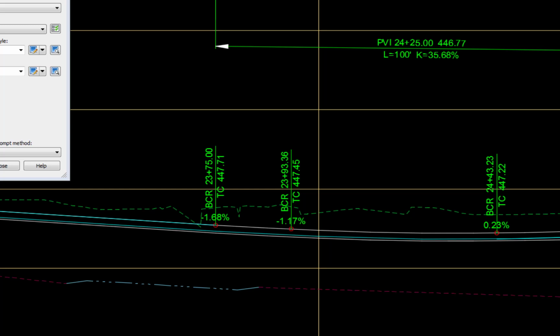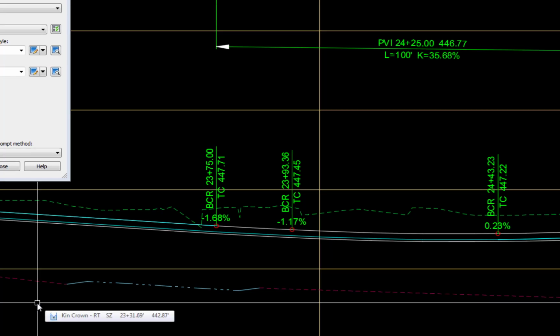And 2. In Properties dialog box, select the appropriate reference object from a drop list. When a label contains more than one reference, each reference is selected separately from a drop list. Where there is only one or few labels with question mark, it may be easier and quicker to erase the label and create a new label in its place rather than trying to correct the existing label. Watch the next video on using the Label Style Composer to create or modify the label styles.